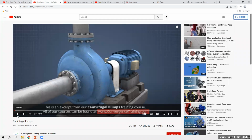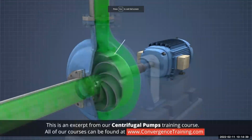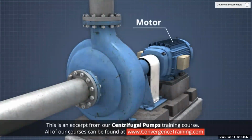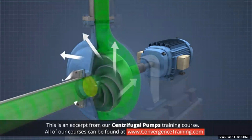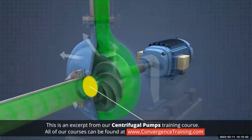Those are obviously short, but you will know the basics. A centrifugal pump consists of a rotating impeller mounted on a shaft inside a stationary casing. An electric motor or some other driver is used to rotate the impeller at a high speed. As the impeller rotates, centrifugal force pushes liquid outward from the center, or eye, of the impeller.